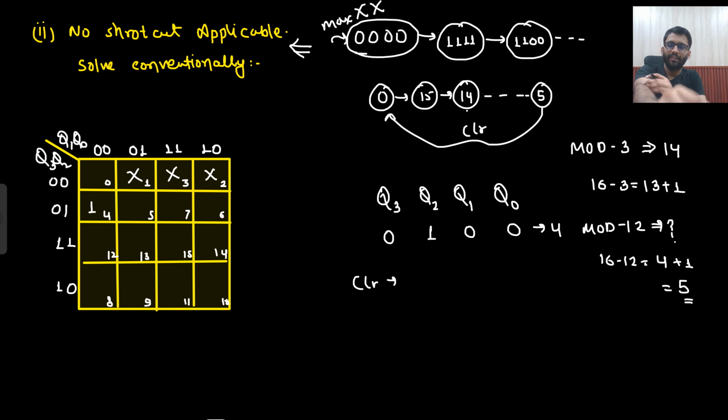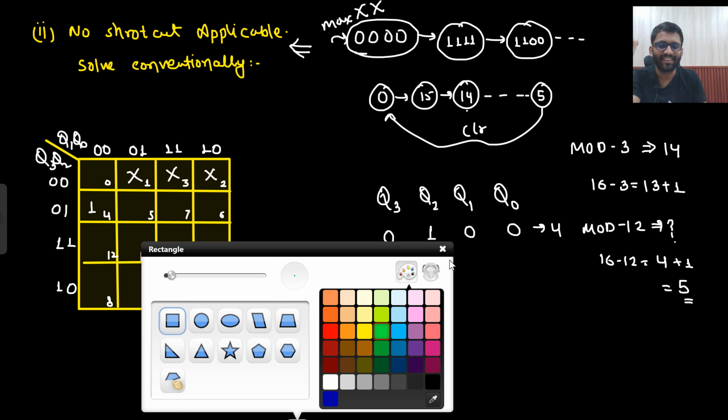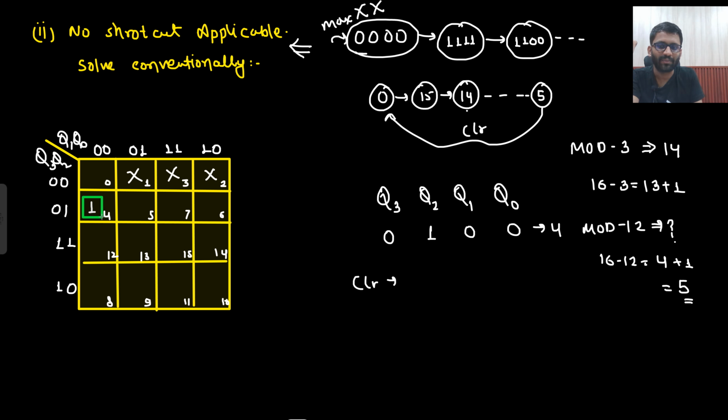But luckily here only one loop is possible, no? So this was not a good example to take actually, because you cannot make any pair here. So the answer that you wrote here would be correct. But luckily you got the correct answer. Let's just say if the don't care was here as well, then there was an issue.